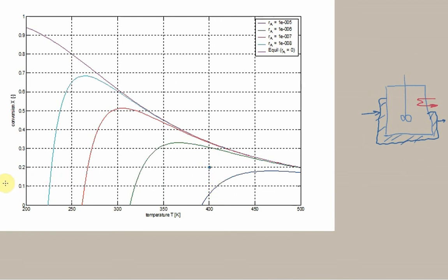So we've managed to convert the reactant to a certain degree. So to 20%, we've converted 20% of the reactant, and we've reached the temperature of 400 degrees here. So what we are saying here is that if we apply heating fast enough, or if we apply cooling fast enough, we could move this point around. We could change the state of our batch reactor left and right like this.